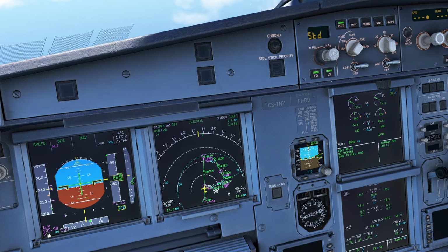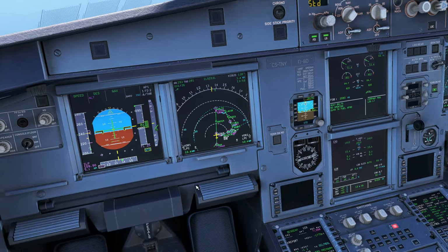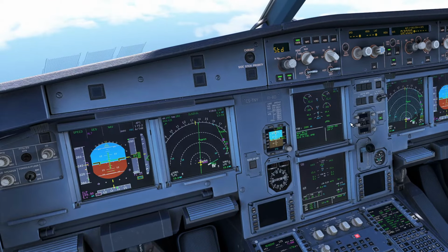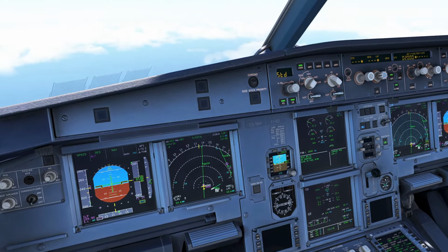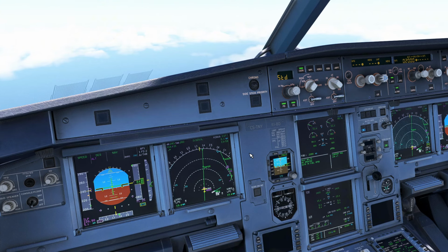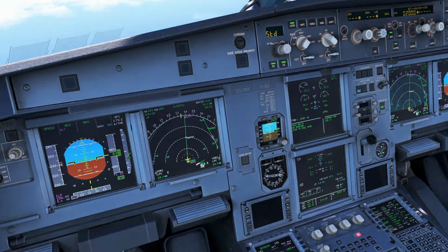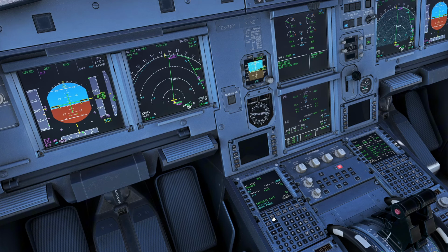India Lima Papa with the frequency 109.9, 5.3 mile identified, and reducing the range to almost 20. Auto brake low is calculated, and I would follow the procedure in managed speed and also NAV mode, that you see how this approach phase will be activated automatically.